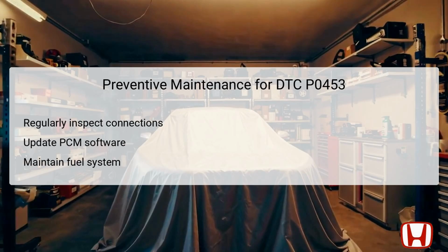To prevent reoccurrences of DTC P0453, implementing routine preventive maintenance is essential. Start with regular inspections of all electrical connections associated with the FTP sensor and PCM to ensure they remain clean and free from corrosion or damage.